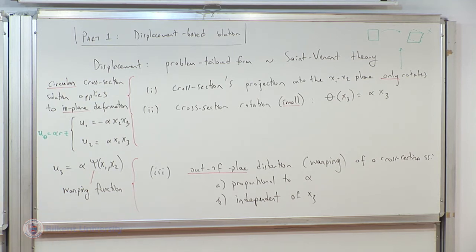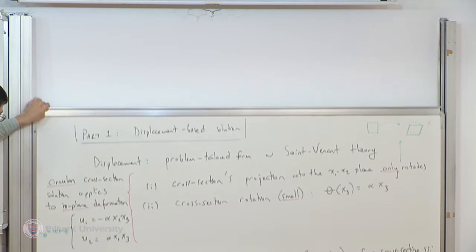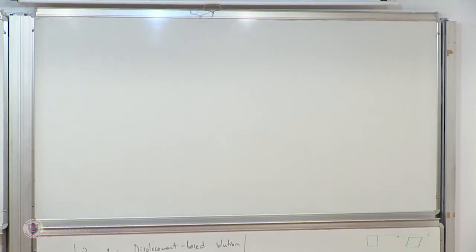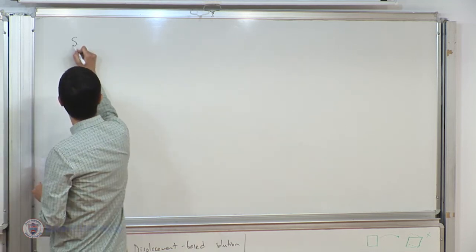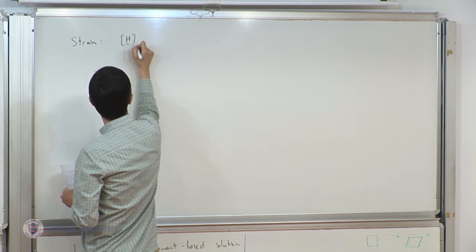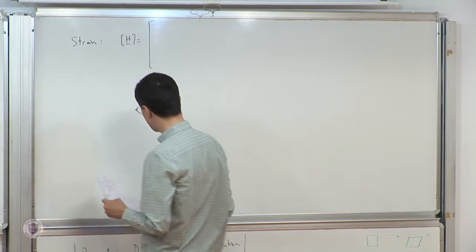So now that we have the displacement, now I'm going to proceed step by step. Strain, stress, equilibrium, invoke boundary conditions, the usual procedure in the displacement-based approach. Okay? So let us do that over here. First, the strain, I'll start with the displacement gradients.